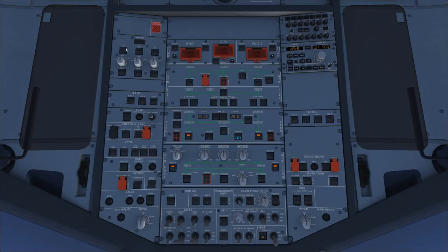You've got three buttons here. You've got inertial reference 1, inertial reference 3 in the center, and then inertial reference 2 on the right. Now you cannot click on these buttons to turn these systems on or off. However, you can rotate these knobs between off and nav to turn them off and on. They do also have an ATT function, however that is not simulated in this aircraft. Also at the bottom you've got three more buttons. You have Air Data Reference 1, 3 and 2, and again you cannot click on these buttons.